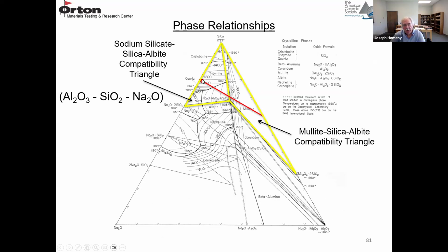material. So this is a real simple example, but this is what you want to do if you're doing studies on potential corrosion issues. You can get your composition of the refractory, your composition of the slag, and see what happens as the composition changes. And this is a really simple diagram, a two-component refractory, a two-component slag.